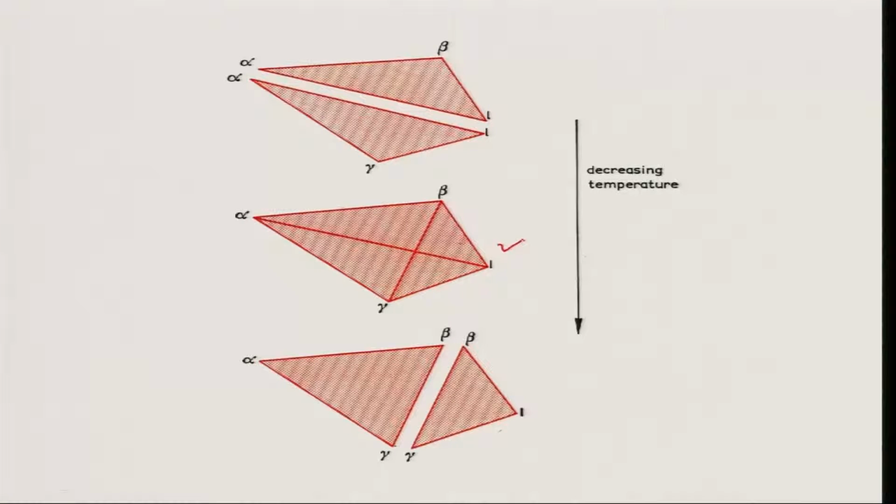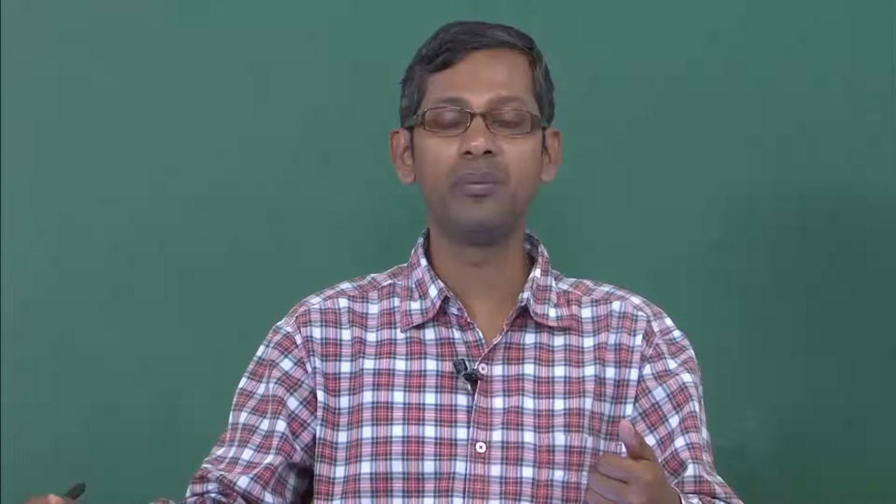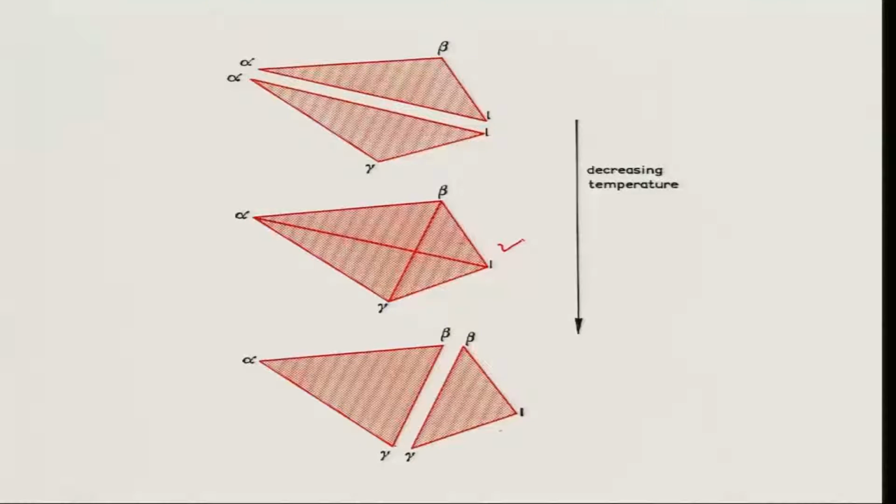These 2 equilibria must exist prior to the 4 phase equilibria, and as you decrease the temperature, the exit from the ternary 4 phase equilibria will happen with 2 three-phase equilibria again.